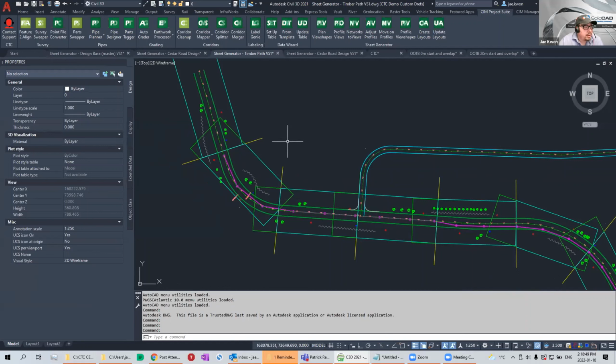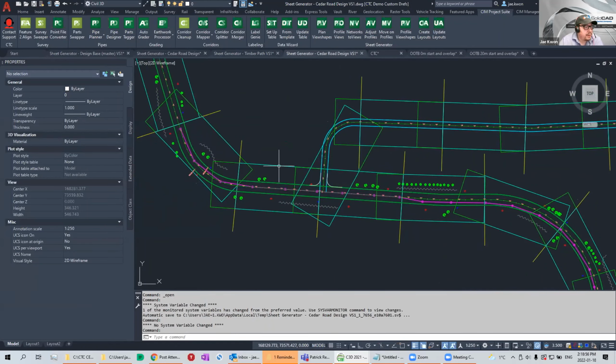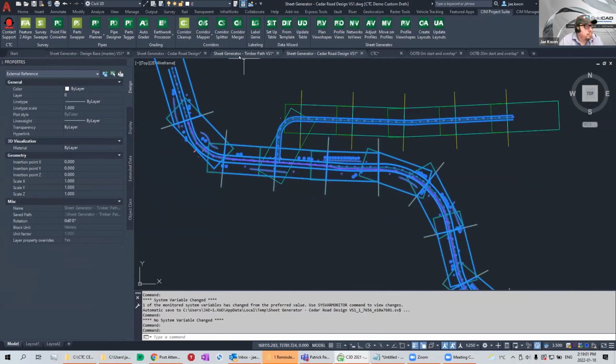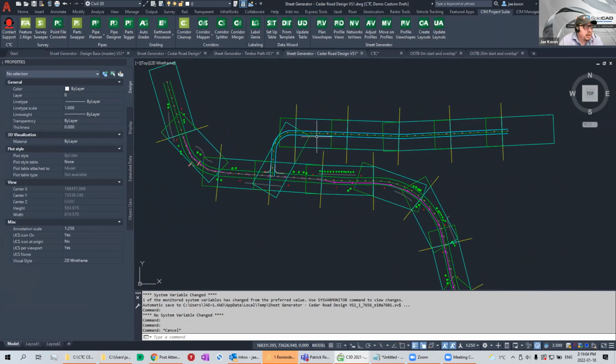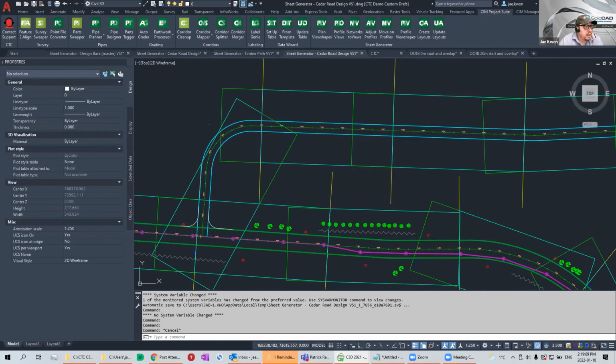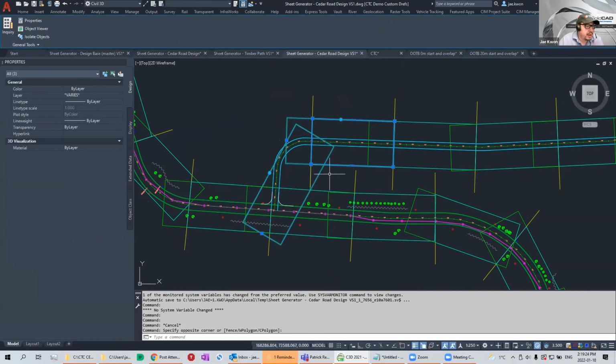When it comes to doing the cedar road, just do another drawing, XREF in the original timber path drawing, and simply do another design, like another alignment, profile, and so on, in the separate drawing. That way you can just run the tool and not have the two different layers clash, because when you do the new set, that would be the only one that exists, right?